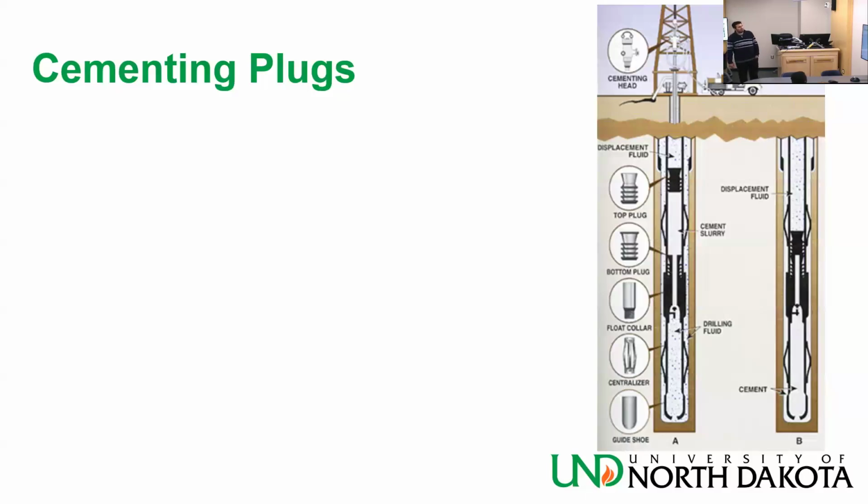And this is how you drive it. Now let's see what we have here. Oh, and at the top, you see the cementing head. The company that is doing your cement job, basically Halliburton or somebody, is going to bring their own cementing head and attach it on the top of the well, and they will pump the cement from there.